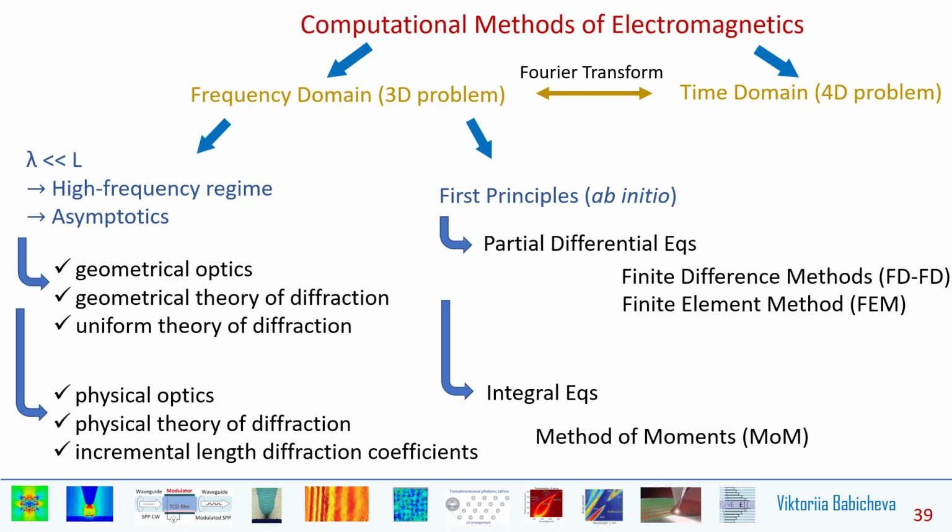If we use a Green function or convert the partial differential equation to an integral equation, then we have the method of moments, and the method of moments produces fully populated matrices, and researchers have developed a whole set of fast algorithms to handle the method of moments efficiently. There is a family of fast algorithms that can be used to speed up the method of moments matrix solution.